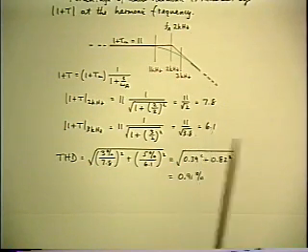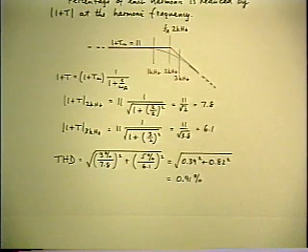So the conclusion from that is, which I'm sure you know already, in order to make a respectable feedback amplifier, you have to keep the loop gain itself high over the entire range over which you want to get the benefit of the feedback reduction factors, which means you want to keep a high loop gain of 20 dB at least, not from 30 hertz to 2 kilohertz as it is in this example, but you want to keep it high over the range maybe 20 hertz to 20 kilohertz.